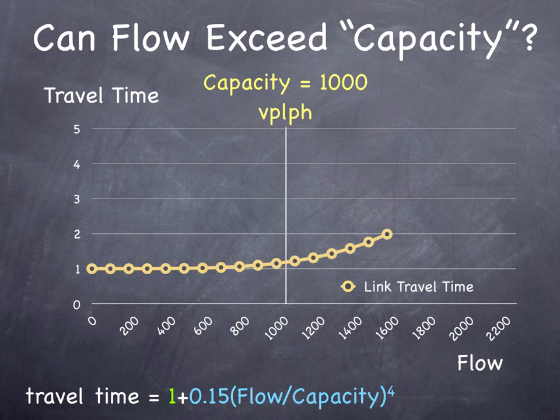Queuing occurs when demand exceeds capacity. You use the link performance function to estimate this cost. On a link, the capacity is thought of as an outflow, demand is an inflow. If the inflow is greater than the outflow for a period of time, there is queuing and delay. For example, for a 1-hour period, if 2,100 cars arrive and 2,000 depart, 100 are still there. The link performance function tries to represent that phenomenon in a simple way.